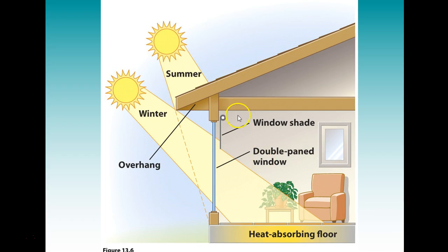So here we see some of these things working together. In the summer, the awning prevents a massive amount of the sun's energy from getting into the house, meaning less energy is needed to cool it. In the winter, the double pane windows allow the winter's angled sunlight in, but trap the heat energy. Materials in the floor allow that energy to stay trapped inside, and they use what's called thermal mass. So items or building material that's specifically designed to keep heat in.